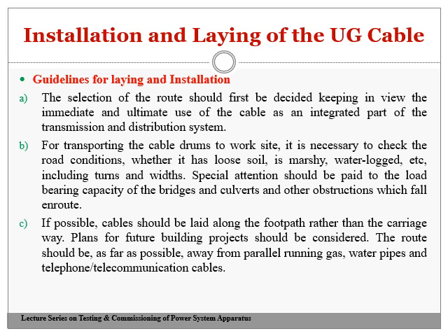Plan for the future building project. As I said, beyond the current capacity, we have to plan for the future development of our projects, taking into consideration an additional 10 to 15% load that may be on the cable. Once in 5 or 6 years, that specification is to be checked, and then rectified by replacing the present one according to the situation which demands it at the particular point.